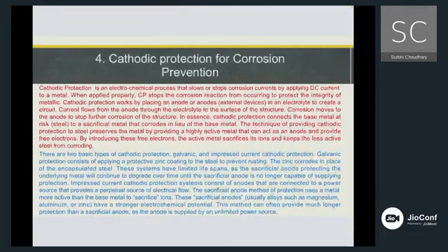Here we can see galvanic protection consists of applying a protective zinc coating to the steel to prevent rusting. The zinc corrodes in place of the encapsulated steel. Basically, if we want to protect a particular metal, then a more reactive metal is taken as an anode in order to protect the metal from corrosion. This is the basic concept of the cathodic protection method.